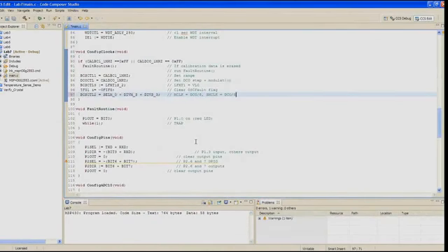In step 19, we need to change the clock settings for the basic clock control register 2 from SELM selection 0, DIVM 3, and DIVS 3. We need to just go ahead and change all those to 0. So make that change in your config clocks function.